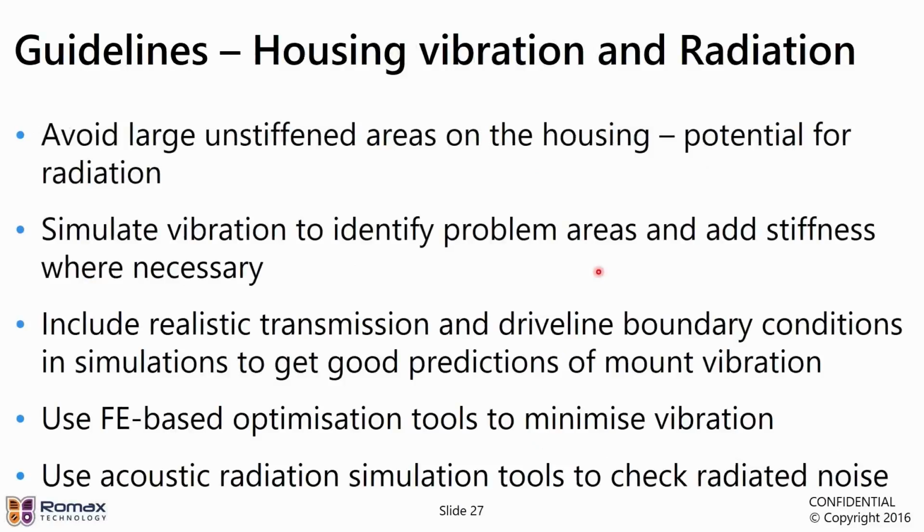They have a very large potential for radiation, and we can simulate that behavior, as we'll see shortly. We obviously want to simulate the vibration to identify those problem areas, and based on the results of that simulation, we can look at adding additional stiffeners, ribs and so on to the housing where necessary to help improve the vibration.